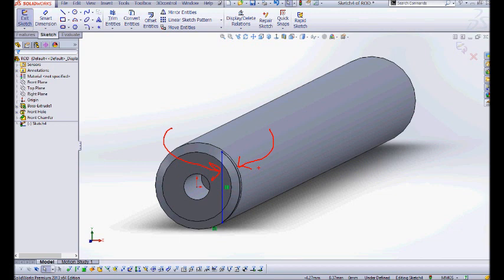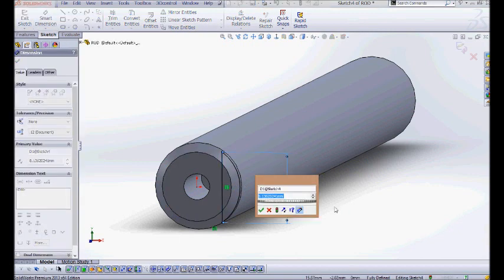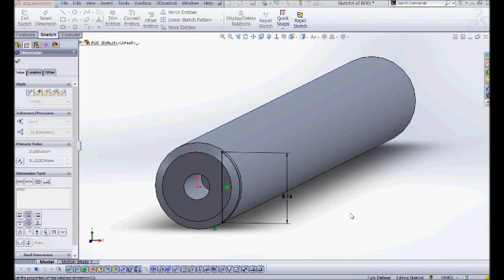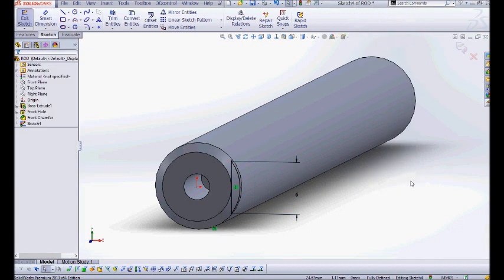So in the exercise, you're going to use what's called the power trim, which is this very first tool. Notice this is what's shaded down. Now, the power trim is, imagine you're holding a giant machete and you're going slash, slash, slash, like a ripper, like a ninja. If you're not careful, you will destroy geometry you want to keep, so you have to be careful about how you use it.